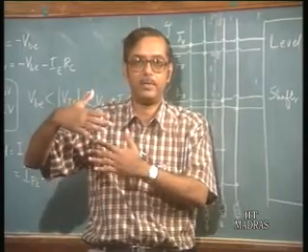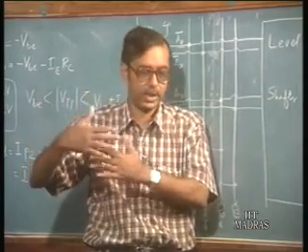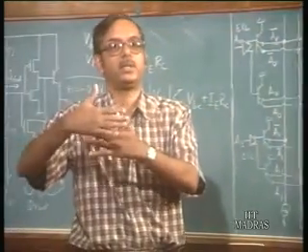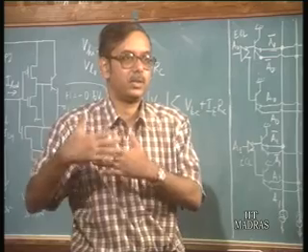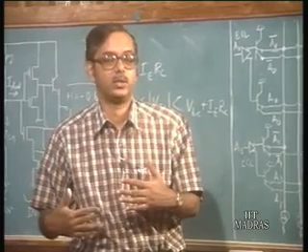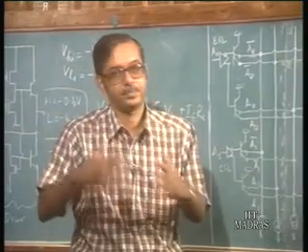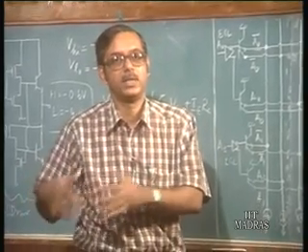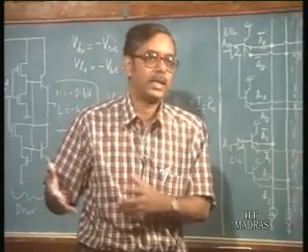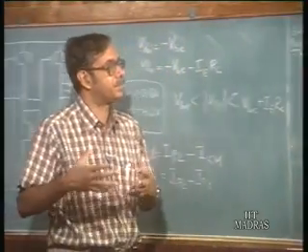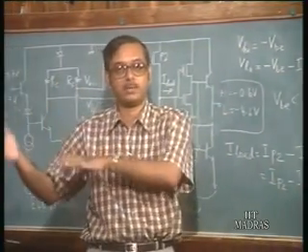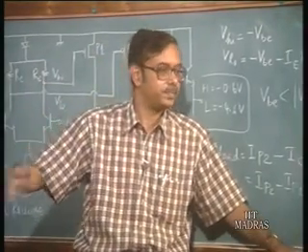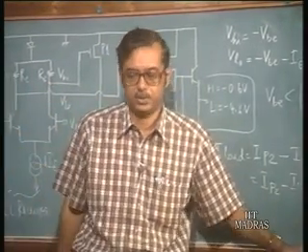So you have almost a full 5 volt, or if you are operating at 3.3 volts, almost a 3.3 volt difference between the high and low logic levels. You can use all the voltage levels shifted down to negative values by the same amount. So you can get basically the same CMOS operation, but one must remember to revert back to ECL levels at the output stage.